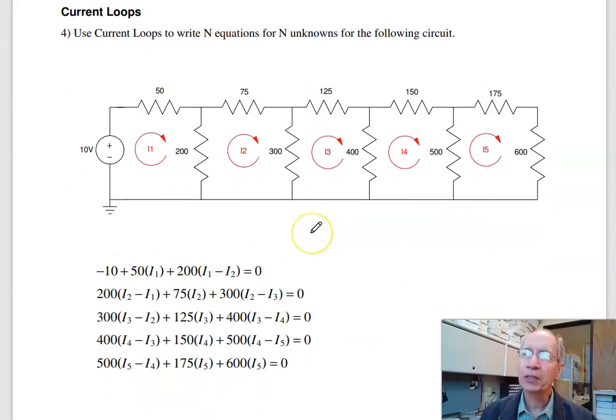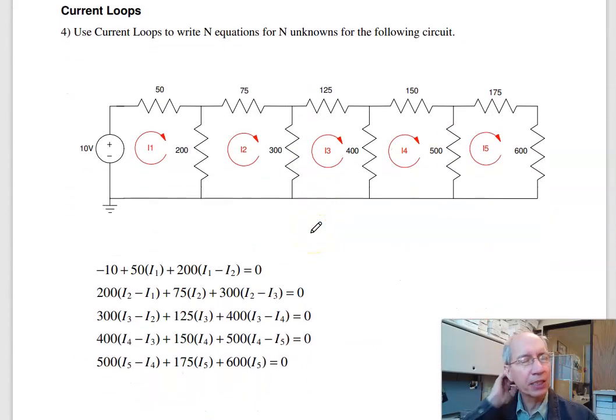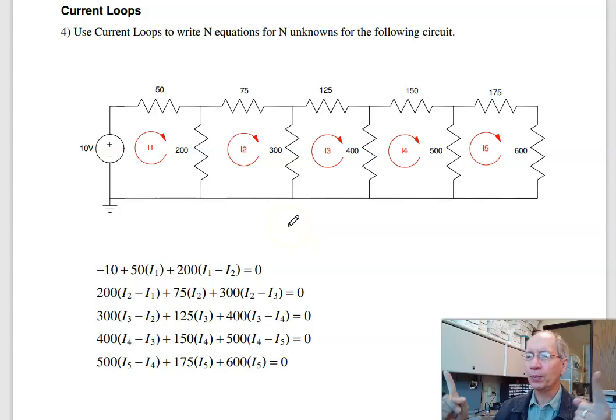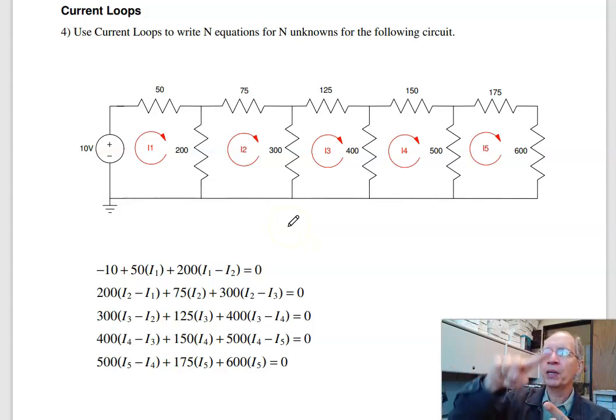So that's one way to solve circuits that you'll be covering in 206 Circuits 1. Set up the problem as n equations and unknowns. There's another approach called current loops. If I take a voltmeter, take the leads and shorten together, I get 0 volts. If I go around a closed path, wind up where I started, I should wind up at 0.